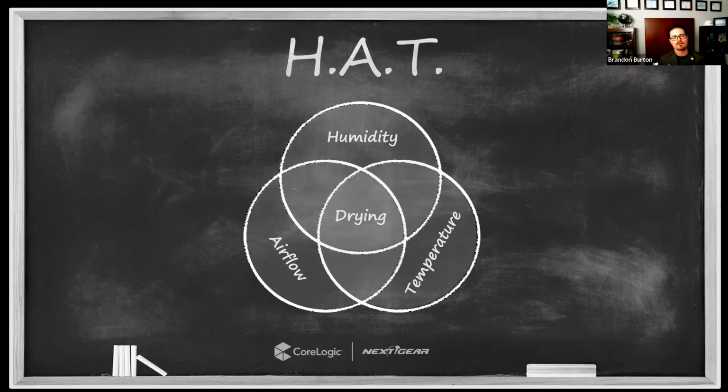And that's part of the concept of HAT, understanding not only that all three of these are important, but where they're important and how we measure for it. So as we get into balancing the drying system, one concept that's really important to hold on to, one of the industry's best kept secrets, is that your psychrometry isn't a hygrometer held out at chest level, right? That psychrometry is important, but it's not the psychrometry that's doing the work. The psychrometry that's doing the work is the air in contact with the wet surface.